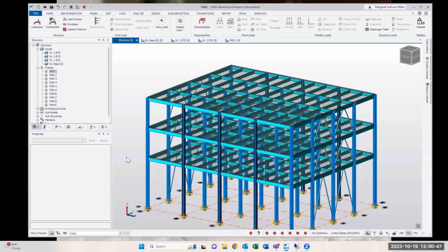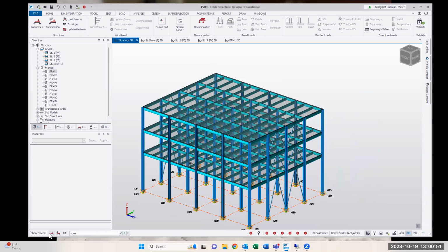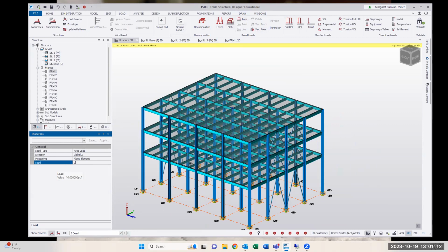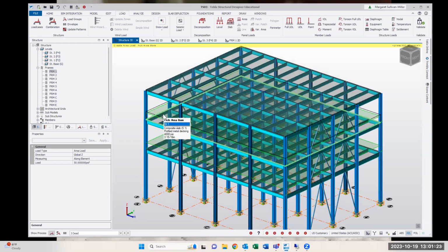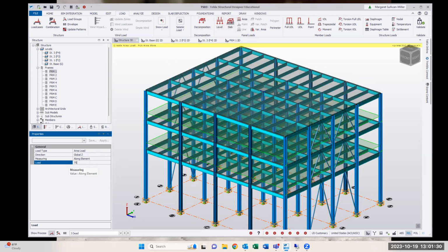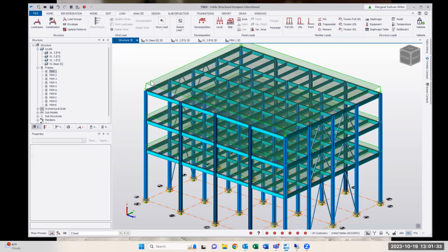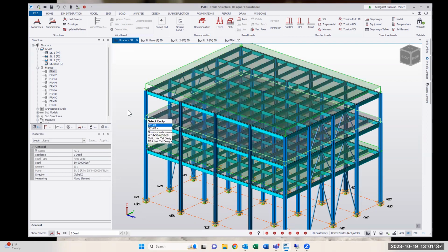Now I'm only going to do one actual load because it is already 1 o'clock. In order to do the load with Tekla Structural Designer, first you have to come down here. This is load cases, this is load combinations, this is your envelope, but you have to choose dead load. And let's say I want an area load. So I'm going to choose this guy. I want to add an area load. Let's see here, let's go with 50 pounds per square foot, right? And then I can click here. And because these levels aren't unique, it created on both levels. But I also know that I have an area load of 75 pounds per square foot for the roof. So this one's now 75 pounds per square foot. This one is 50.